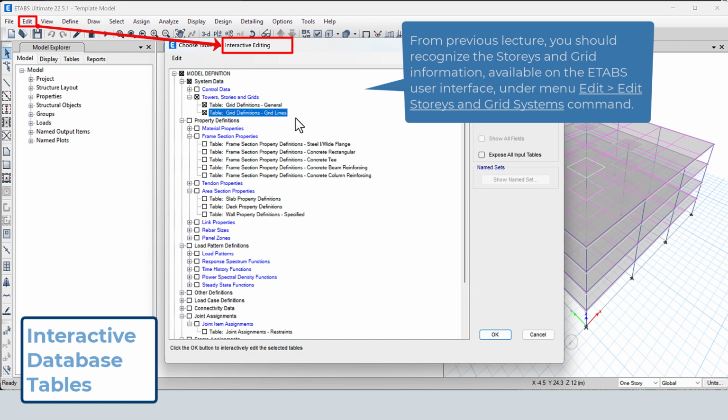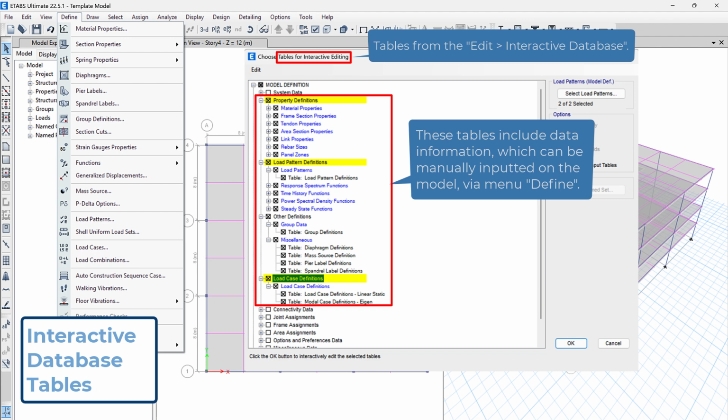The reason that table is not there yet is that the interactive database feature was actually inherited from the SAP 2000 program, and in all the portfolio of CSI software, only really ETABS recognizes the story concept, which explains why CSI hasn't yet added the stories information table here, but I gather we might be seeing it available in a not-so-distant future.